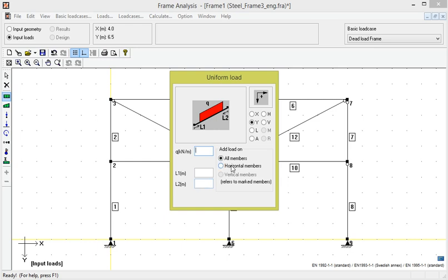The uniform load can operate in the global X or Y direction, the local direction, meaning perpendicular to the direction of the member, or as an axial load along the member. Furthermore, the load may also operate horizontally or vertically, meaning at a horizontal or vertical length instead of the total member length for skew members to, for example, simulate snow load.